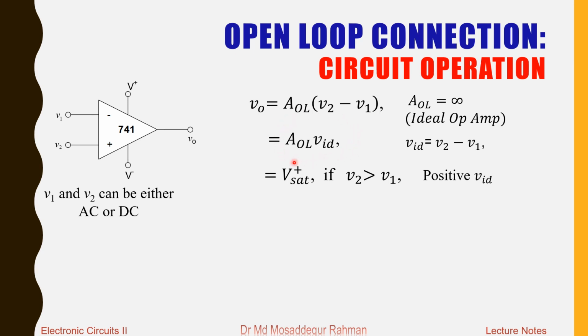Op-amp is a tiny device, of course. Forget about infinity, you cannot even get 100 volt. 100 volt is too high, if you apply 100 volt to an op-amp, it will just melt. The maximum voltage applied to the op-amp are the supply voltages, and the maximum is about 20 volt. Usually it varies, 10, 15, different op-amps have different specifications, but usually the maximum voltage would be about 20 volt.